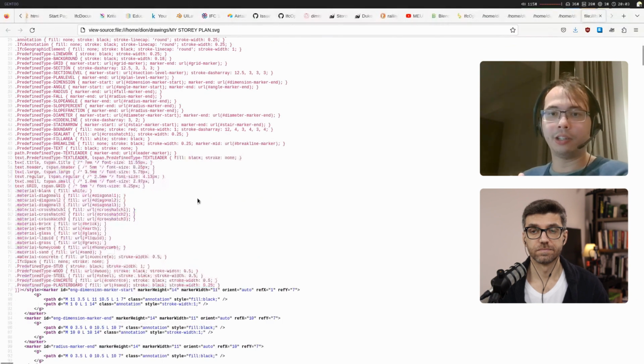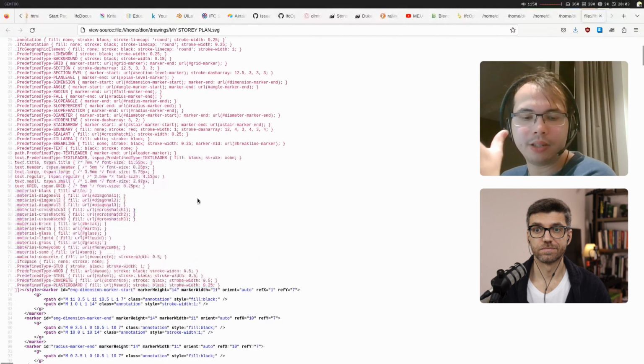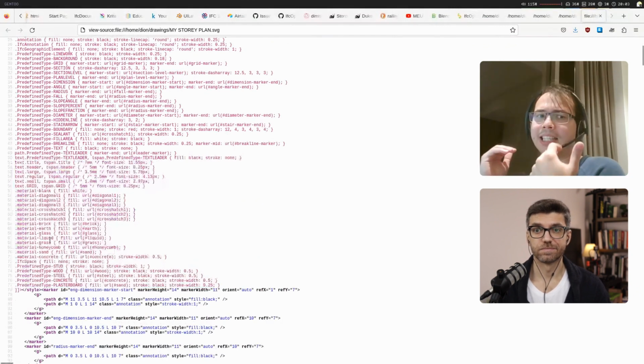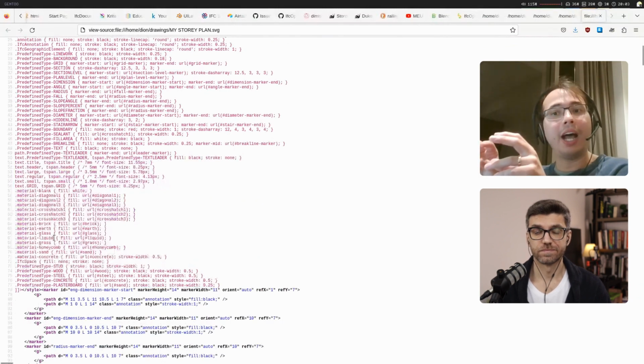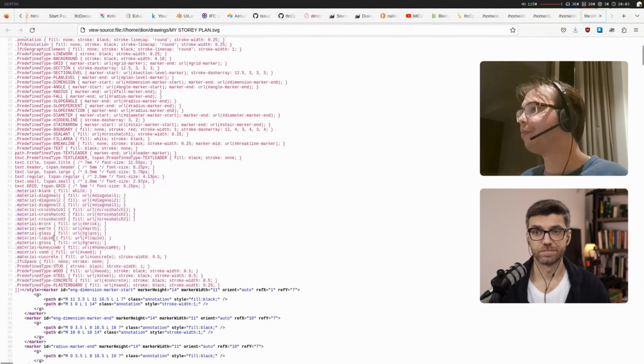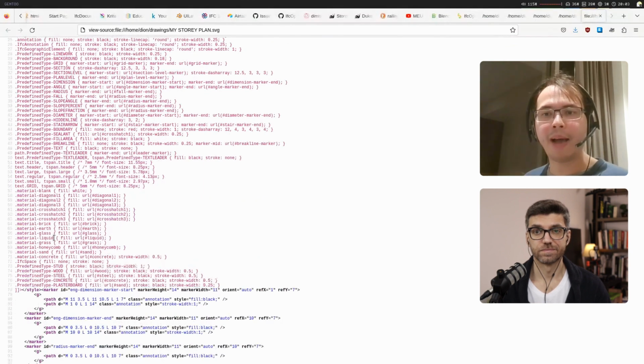So you can create your own definition saying that all concrete uses this hatch pattern and has this line thickness and such and such. And exactly as you would do it in Inkscape, you just distribute this little style sheet file. So this drawing knows that it has this default CSS being applied: this set of markers, this set of symbols, these hatch patterns being loaded in with this drawing. And you can define your own presets. Of course, we ship out of the box with a few.